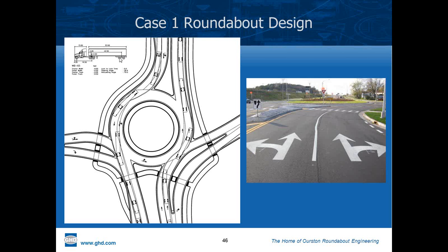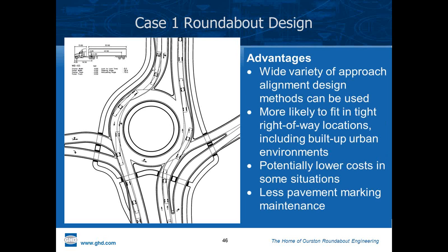53-foot trailer, depending on where you place the rear dollies. 43 feet, I think, gives you a WB-65. I think that's probably the maximum. So to get to a 67, maybe it's 46 or 47 feet. There's a couple more feet to get to 67 from the 65, but there's quite a difference in swept path requirements between the two. So we often design for 65 and test or check for 67 to see if it'll work.